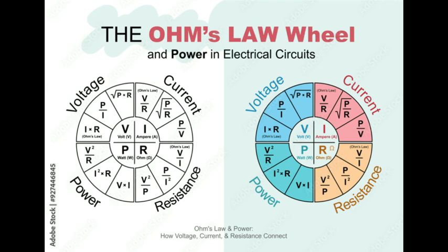because it's gonna go also to the next light. And this is what we call parallel, because we have our neutral coming in from the home run. And then we have our neutral going into the next light, but also connecting to our second light. Our neutral coming right here from the power source, and then going in directly to the last light. So this is a parallel connection. Then we have to interrupt our power with the switch, because we want the lights to turn on only when I turn on that switch.